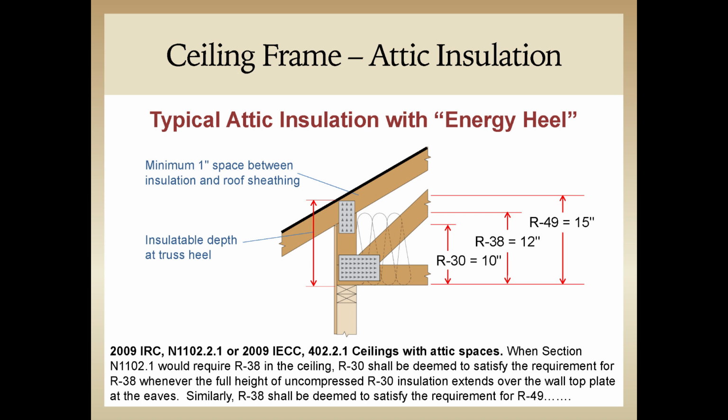The Energy Code recognizes this detail as an advantage and provides an allowance for reduced attic insulation when it's used. When raised heel trusses are used to meet this requirement, uncompressed R30 insulation is deemed to satisfy R38 requirements, and uncompressed R38 insulation is deemed to satisfy R49 requirements. Raised heel roof construction requires an insulation depth of 10 inches for most R30 insulation and a depth of roughly 12 inches for R38 insulation.